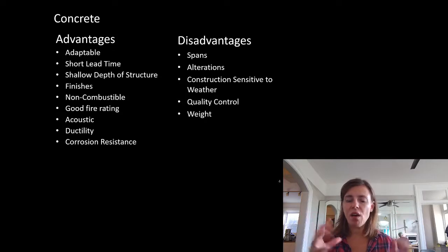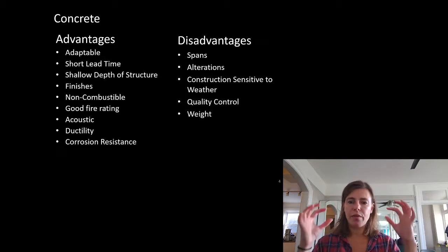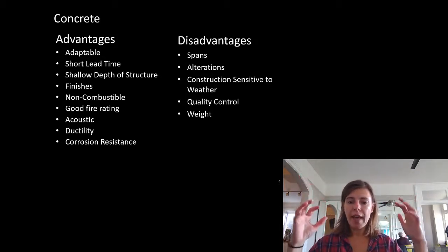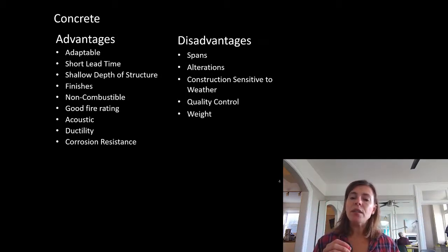It will wick into it. On a rainy day after the sun comes out, you've probably seen that concrete takes a little while to dry. That's because it's got a lot of that water absorbed into it. So that salty water can now come down into the concrete, and steel can rust very easily.